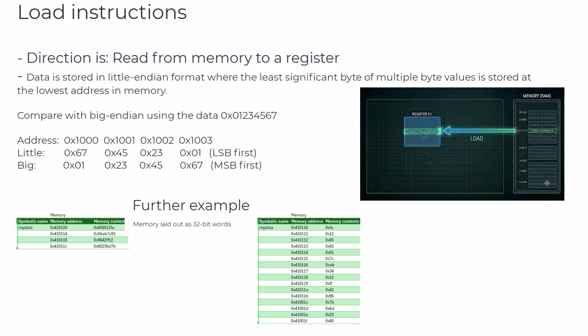Data is stored in little endian format, so this is how the least significant byte in a multiple byte stream would be stored into the lowest address location in memory. So if you had a word of 4 bytes, then the lowest byte would be put into the lowest area of memory. With single bytes, it doesn't matter. It will be put into the next location specified. Some of the other processors will use big endian, such as the Motorola 68 series. In fact, ARM64 can use both formats, but will be dealing with little endian.